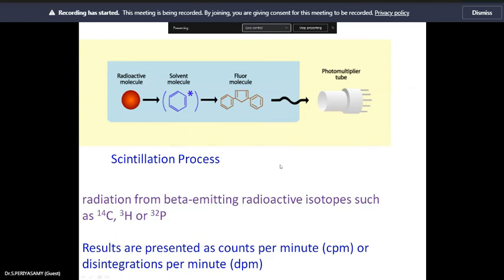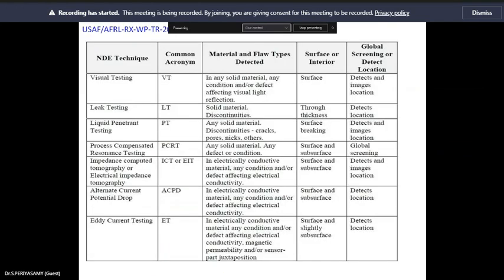Here we can go for computer tomography analysis. In that, you can measure some of the particle size, even some porosities, and other parameters. Here the particular equipment used is a Skyscan 1172 from Microphotonics. Here the equipment image pixel size is 2 micron. The voltage used is 100 kilovolt. The image analysis using micro-CT data was conducted to determine the porosity of the sintered powder.